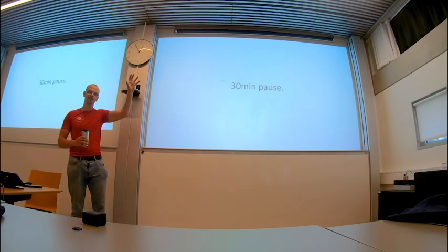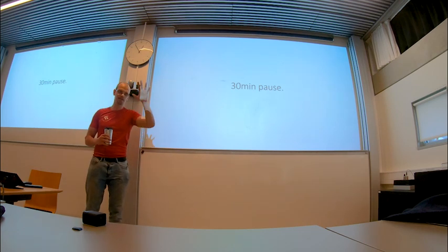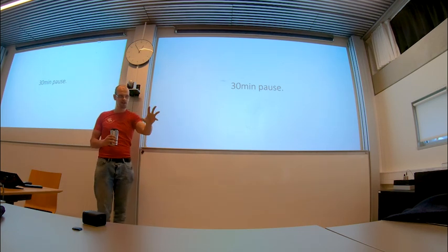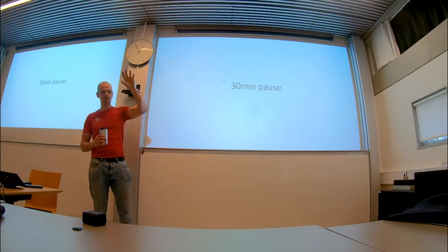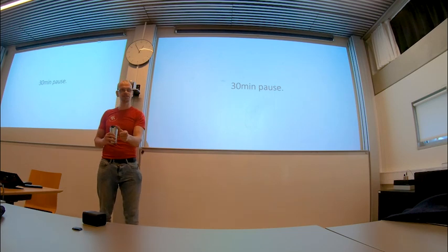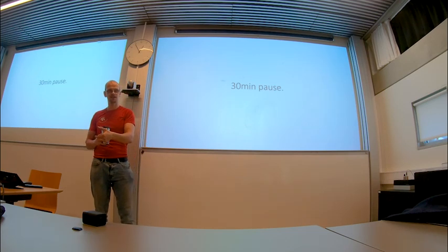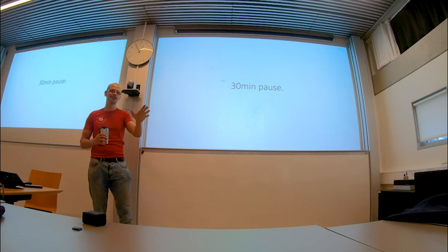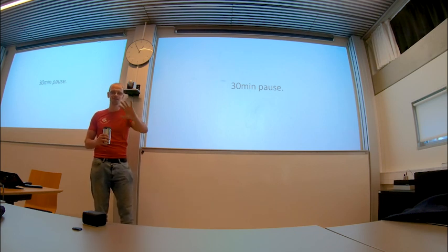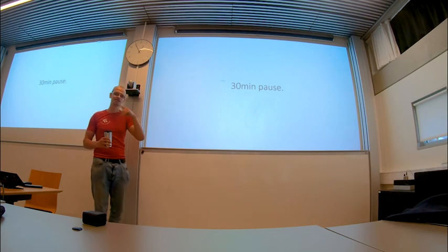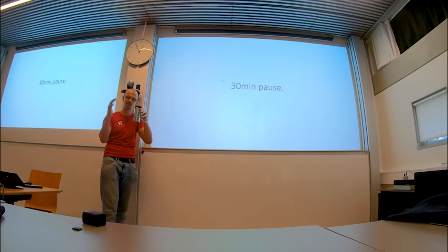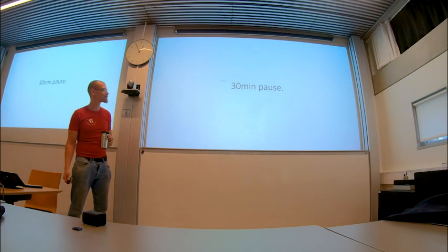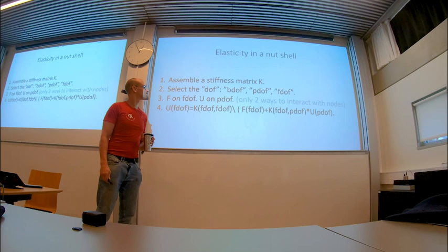Next step, something changes. Maybe you change the load. And in plasticity, there are iterations of adjusting the third F. So apply the deformations, apply the forces, and check if the reaction force matches the prediction of the model. Doesn't match, adjust the plastic forces. Check if it matches. Doesn't match, adjust the plastic forces. Check if it matches. Do it 1,000 times. The bigger the mesh, the longer it takes, because every node shakes in its own way. It's super time consuming. And that brings us to the second part.